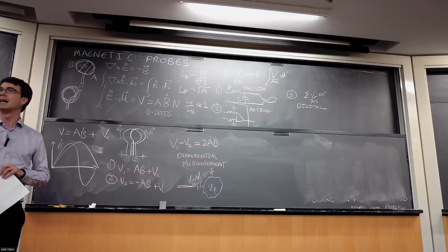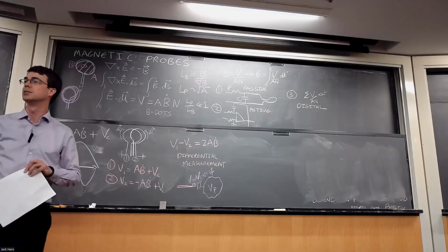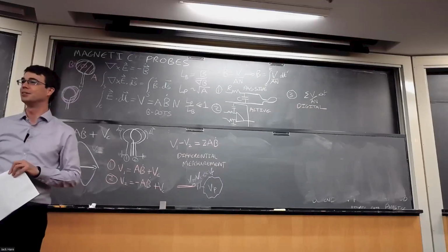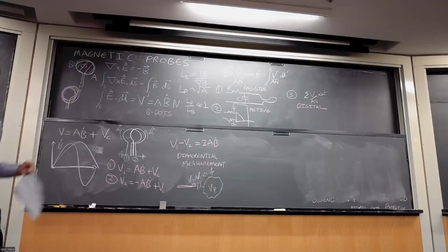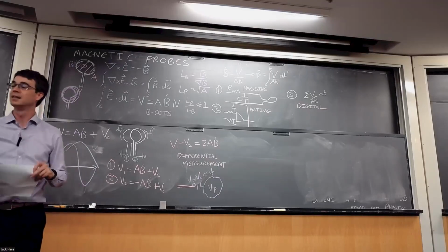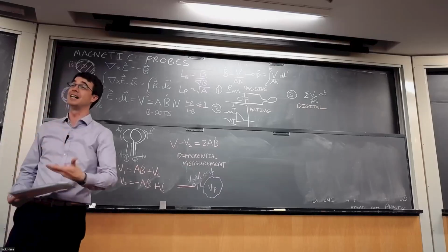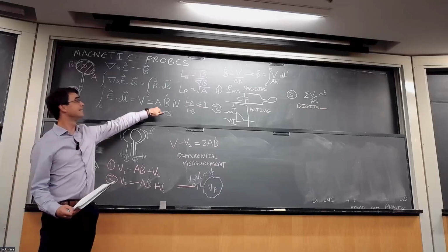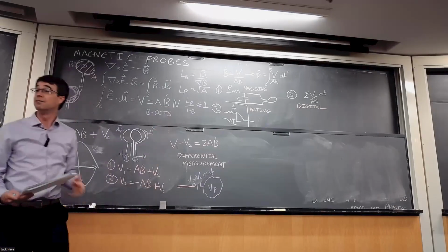Oh, I guess you're right. Yeah, it's going to be relatively small depending on how big your signal to noise ratio is. But you're right. It's like a random walk, so you're going to diffuse away from where you start. I guess as with all measurements, you want to have a good signal to noise to avoid that. You should design, as a diagnostic designer, a system which gives you sufficient signal to noise, which might mean increasing the area of your loop, or it might mean increasing the number of turns in order to fulfill that.